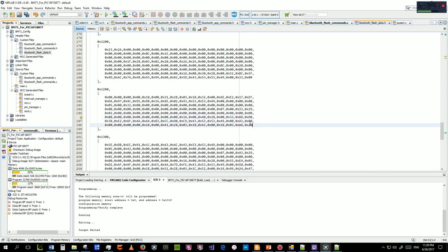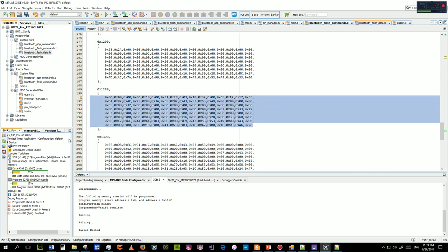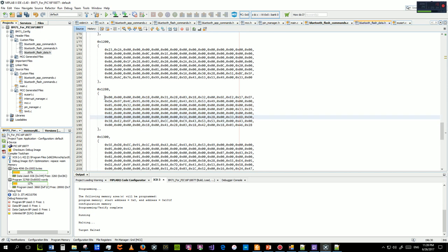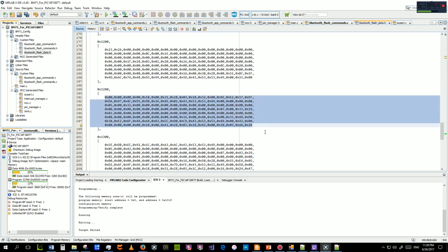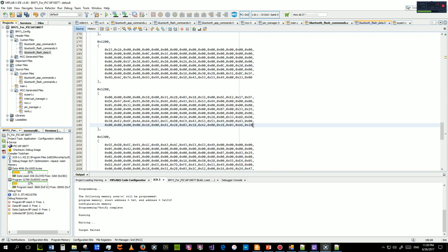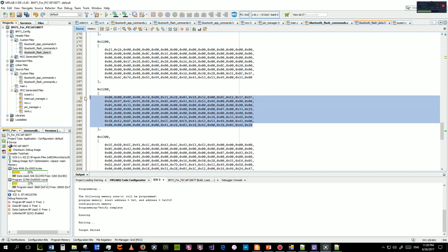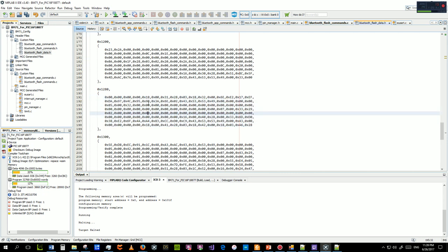One is because you'll probably want this data as a constant, as we talked about, because of the memory issues. You will have to first load the block, the 128 bytes, into your buffer, and then you will have to make the individual commands that will flip the specific bytes you need.